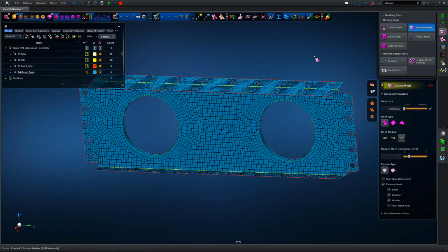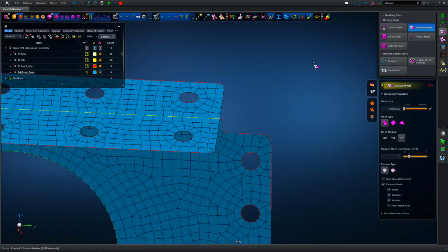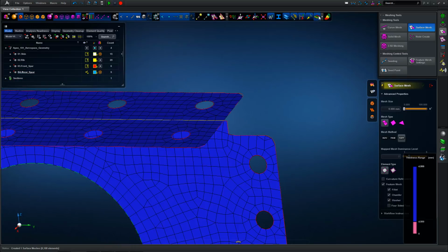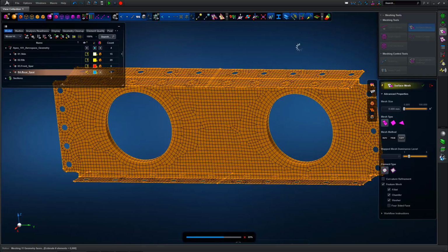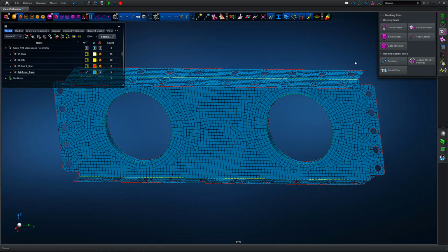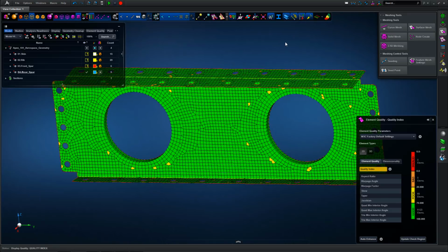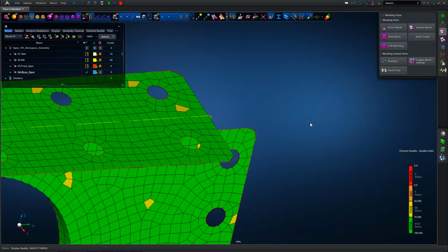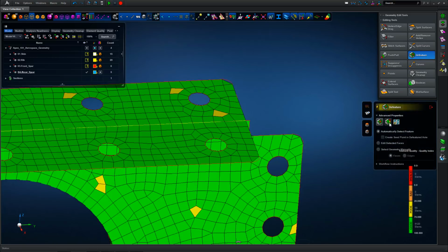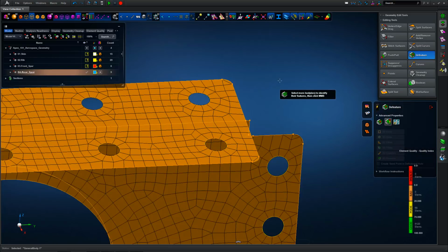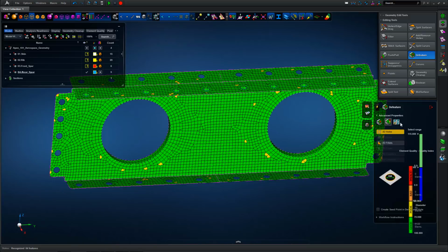So meshing with a 5mm edge length, we can see the washer mesh definition at each hole, the thickness of the underlying property that again was generated as part of the 3D CAD definition, and then we can now start to look at detail, element quality, so live feedback in terms of the mesh definition. So we can see we have 0 invalid elements, 0 bad elements, a number of poor elements, but we're mainly dominated by good quality elements given the meshing algorithm that we've used.